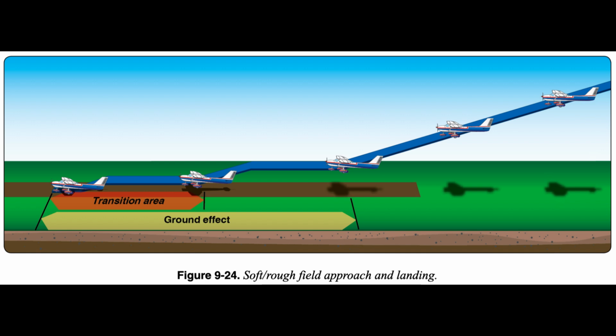End of page 9 to 23. The final approach airspeed used for short field landings is equally appropriate to soft field landings. The use of higher approach speeds may result in excessive float in ground effect, and floating makes a smooth, controlled touchdown even more difficult. There is no reason for a steep angle of descent unless obstacles are present in the approach path.